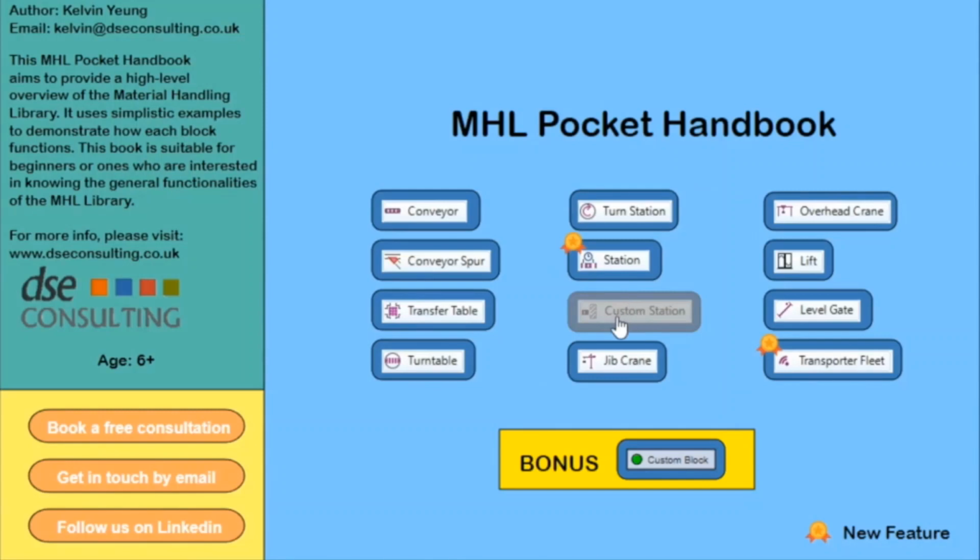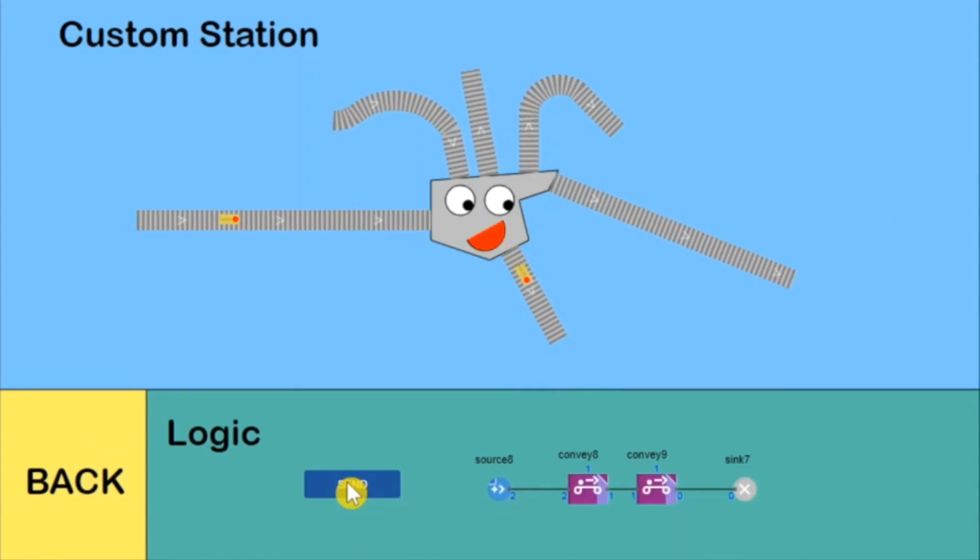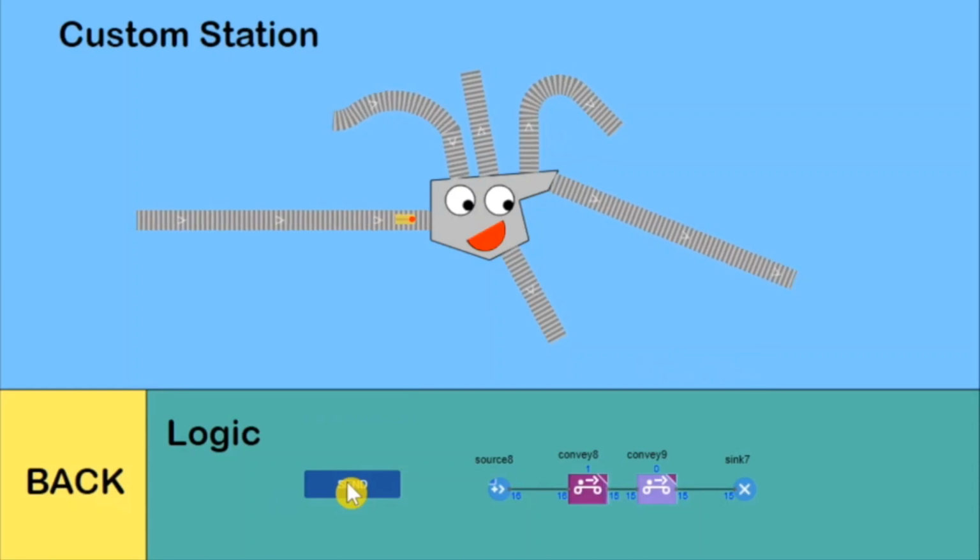Custom station. Custom station is a space markup element used in material handling models. It defines a station or working zone where material items are processed. The process is not set up in this element. You should define it on your own. Custom station can act as a transit point in a conveyor network. Any number of conveyors can lead to or from the custom station. Custom station is drawn as a polygonal area. The shape and size of the area does not have any logical meaning.